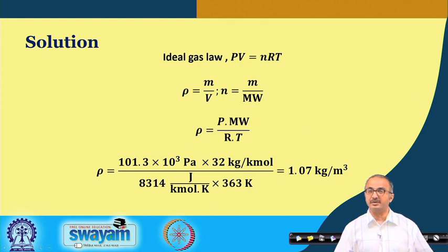So, we are putting in kg per kilomole, and then the universal gas constant, that is 8.314 joule per mole per Kelvin. Here we are putting it in terms of kilomole, so we have multiplied 8.314 by 1000, that is 8314 joule per kilomole per Kelvin. Now, unless we put these units along, initially you may not be able to understand why we are taking these values or in what units. Once you get used to this, then you may not write the units.